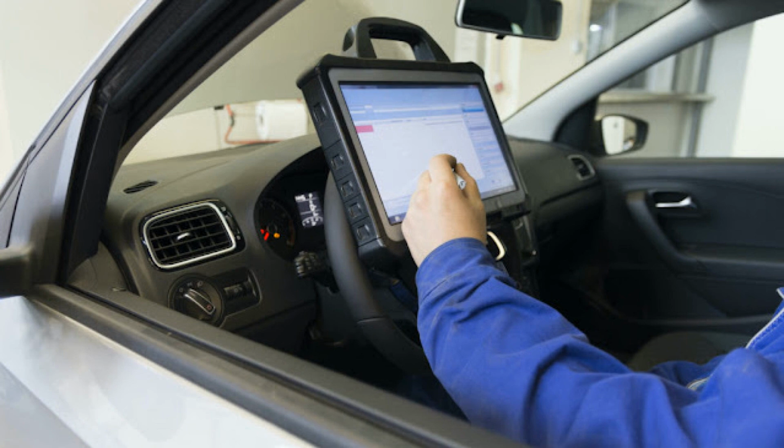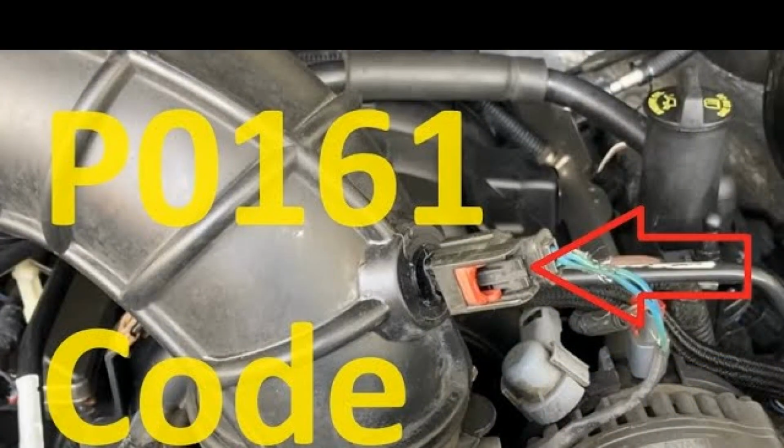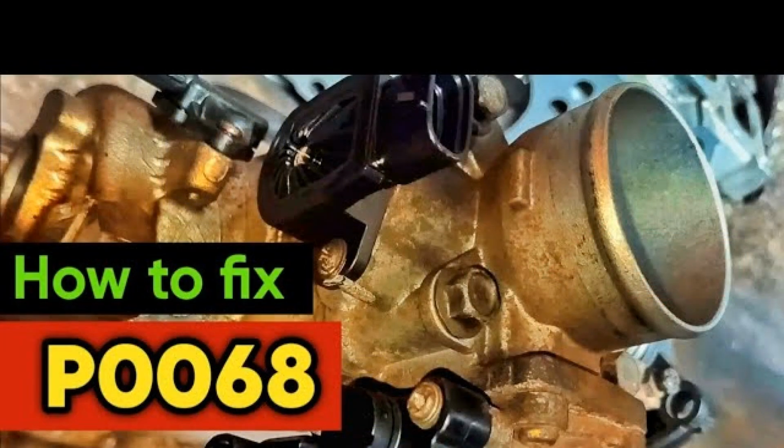For probably 20 years now, engineers have been building algorithms into engine control software to perform what are known as rationality checks. If, for example, the engine is thought to be idling based on the throttle position sensor input and the mass airflow input does not increase when the ECM or PCM increases the idle air control percentage to increase idle speed, the ECM or PCM is programmed to see this as an anomaly. Similarly, if the throttle position sensor indicates that the throttle plate is opening, but the mass airflow input shows no corresponding increase in airflow, this is an anomaly which will set a code.